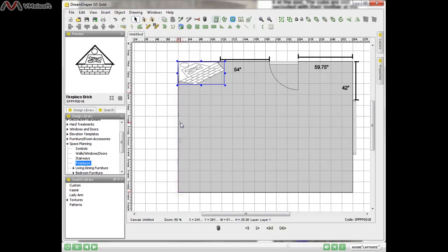So I'm going to draw another dimension tool. Alright, one more dimension tool. So I'll click on my icon, click on the canvas, and I'll type in 105. Now, keep your finger depressed on the Shift key as you draw your line, and this time I want a perfectly vertical line.